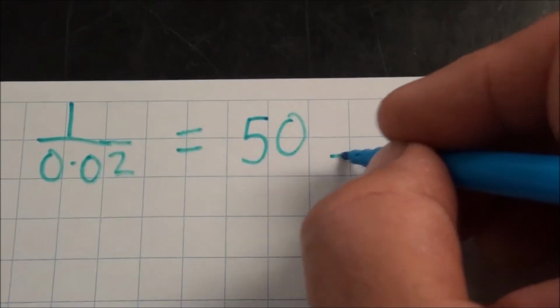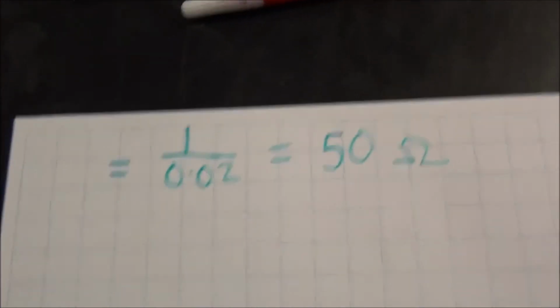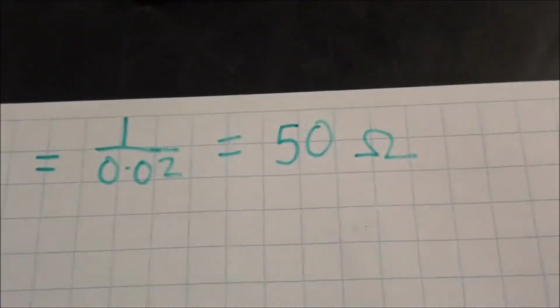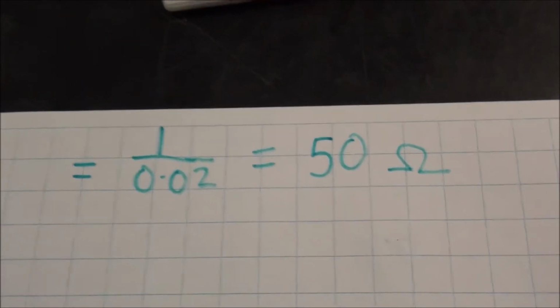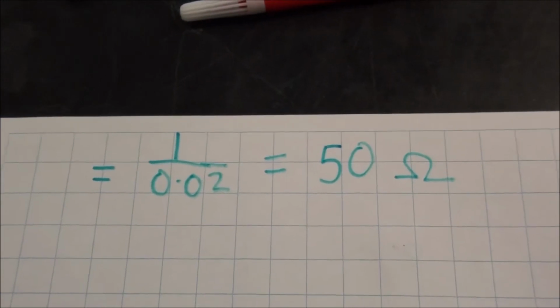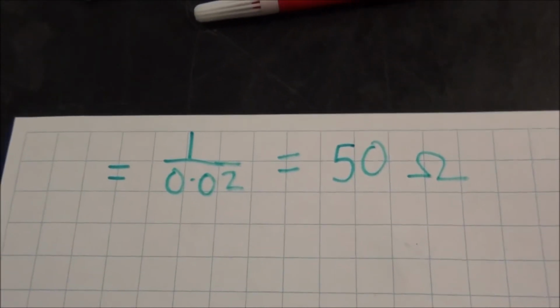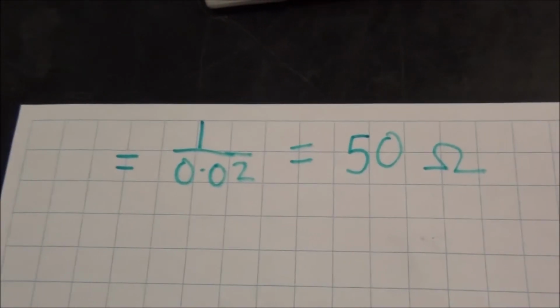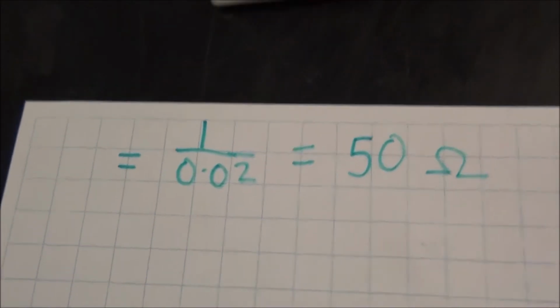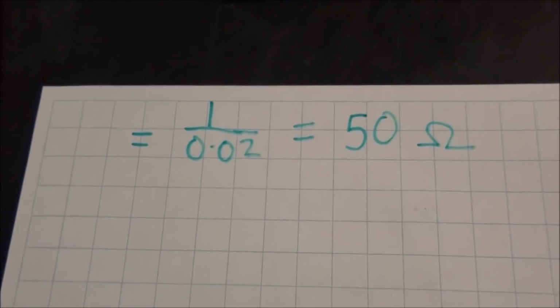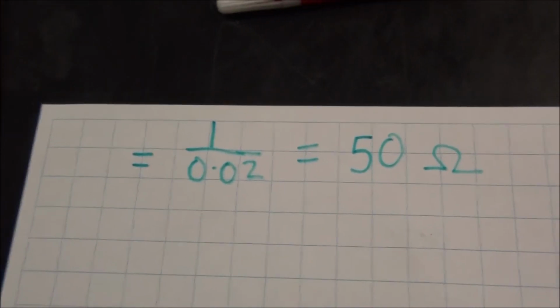So instead of using a 100 ohm resistor, I should be using a 50 ohm resistor. But by using a bigger resistor, more resistance, I'm actually making the light dimmer but also prolonging the life of the LED. So not a big deal. I assumed 3 volts for the LED. It should really be 3.7, but that's okay. It'll be fine. As long as the voltage drop going across the LED is not too much or not too little, it will still work.